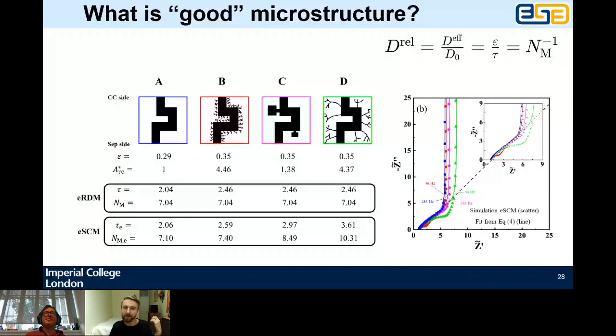Given the heterogeneity of the microstructure, the periodic boundary conditions might be very huge in number. I'm not quite sure I understand that one. The point really is just that we can generate a structure that looks like the real stuff, but we can also trick it into thinking it's in a spherical universe, if you want, where what comes off one side goes in the other. So for a given size, our microstructure will look a bit more representative than a non-periodic structure of the same size. So it just means your computations become a bit more efficient.